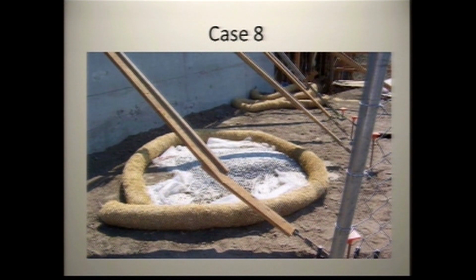It's because the main thing we're worried about is changing the pH of the runoff water. You know, the water's going to hit this, pick up all the concrete, and blow right through the wattle. The wattle's going to do nothing to enhance or reduce or eliminate the pH change that's occurred. So this is just, you know, somebody knew they had to do something, but they weren't too interested in really doing much more than trying to apply the eye wash.